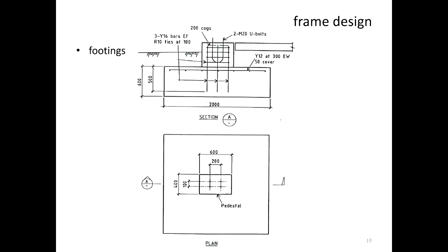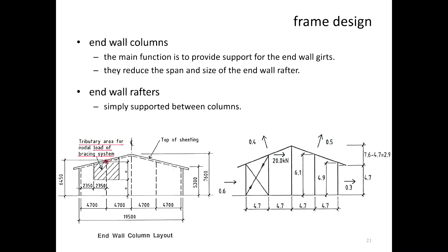Okay? So when you have the end, the end wall usually is not a portal frame, because it has a lot more members in it than just a portal frame. When you go to site, you will see that, because we're going to see a naked structure. The end one will be built differently than a portal frame that's got a portal column, a rafter and a portal column in the middle and so on. Because these are the ends, if you have a lot more members in there, it doesn't matter, if that makes sense.